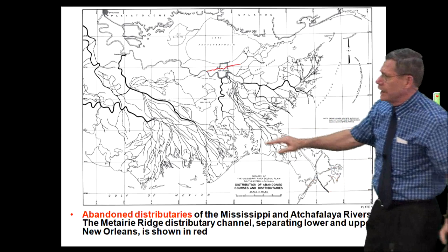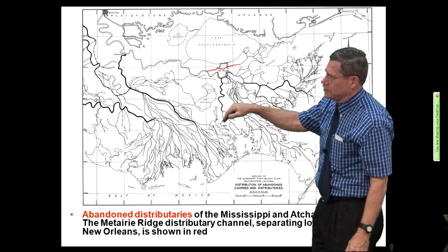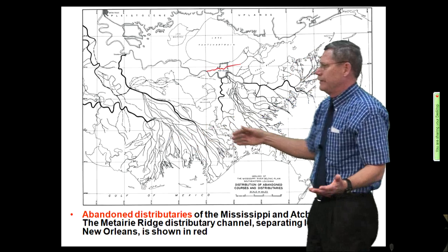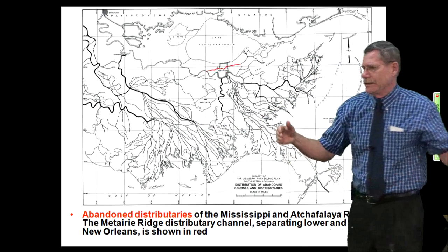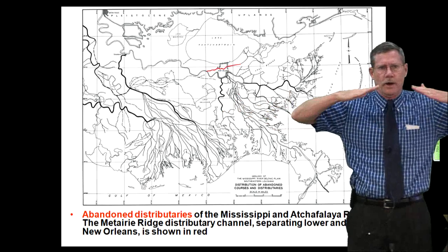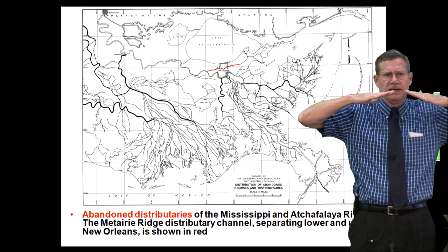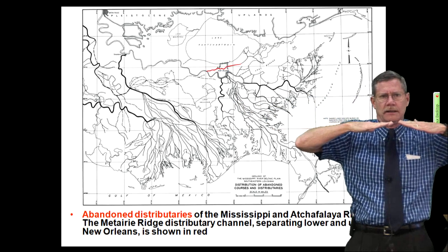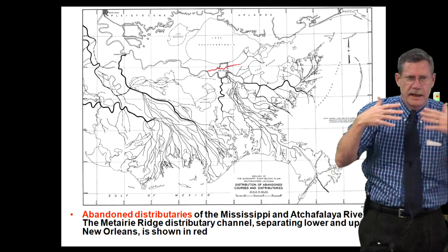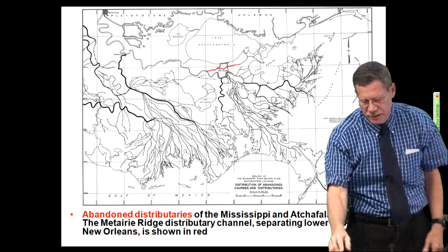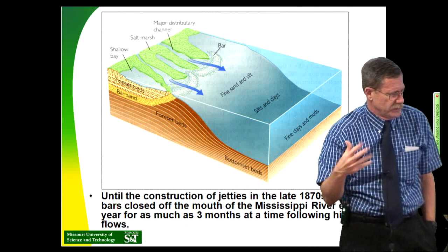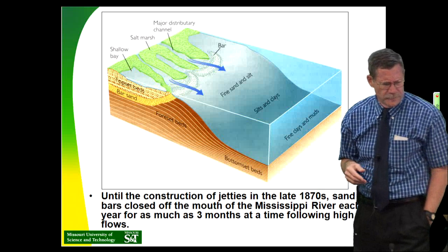And that's why when you go down here in Terrebonne Parish and you try to build an 18-foot high, 100-year flood dike, it's got to be about 1,500 feet wide with 1 on 16 slopes, and even then it's just sinking into the peaty soils of the swamp, and you just have to keep adding and adding and adding, and it keeps sinking and sinking and sinking. And it's a good deal if you're getting paid by the yard. I mean, you're going to have a lot of work there. You're just going to keep feeding the monster.